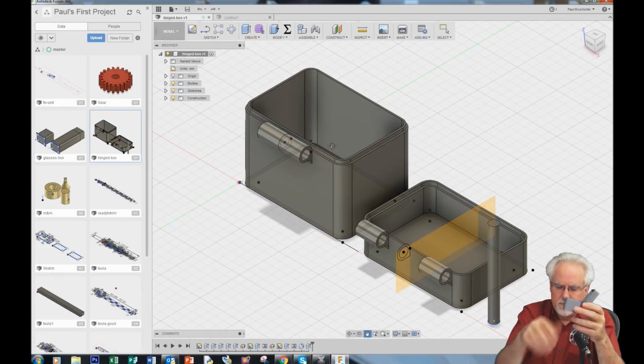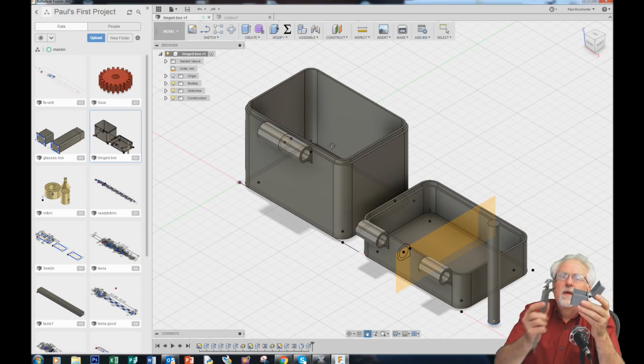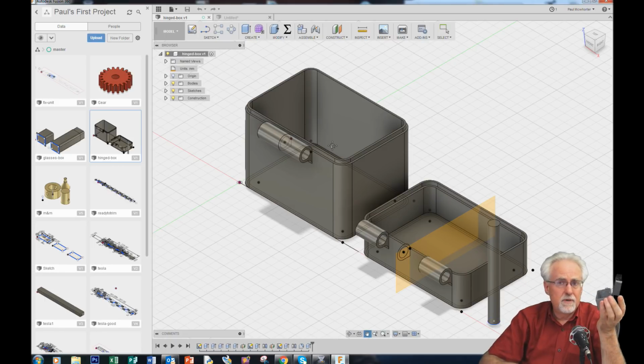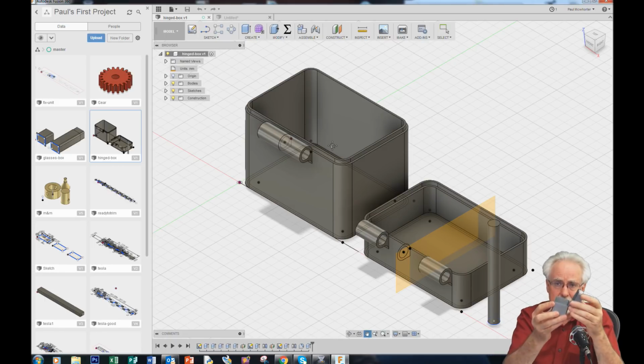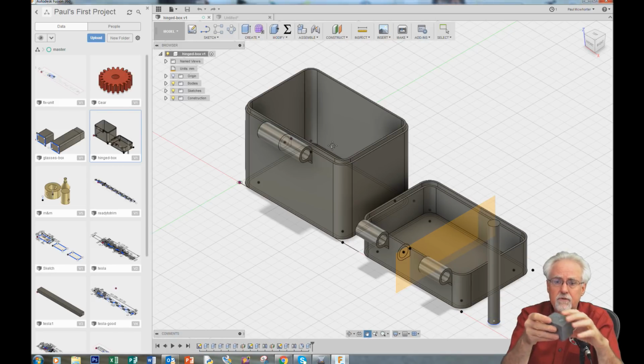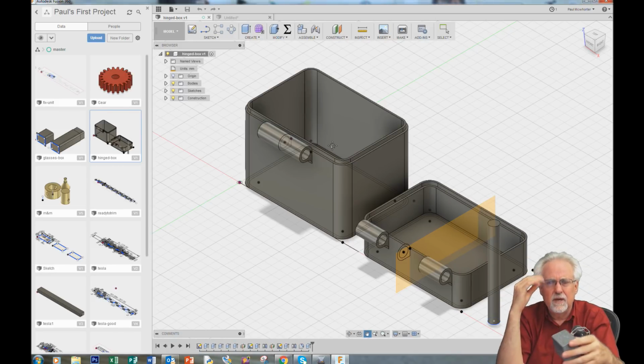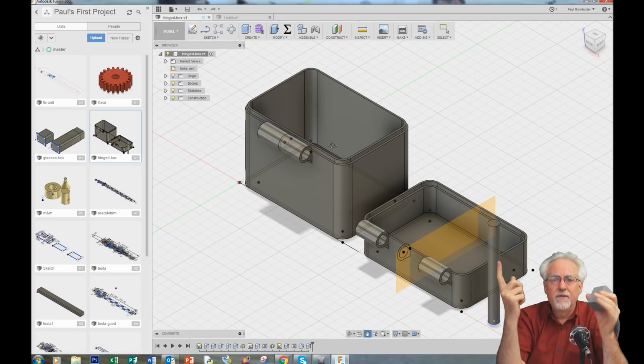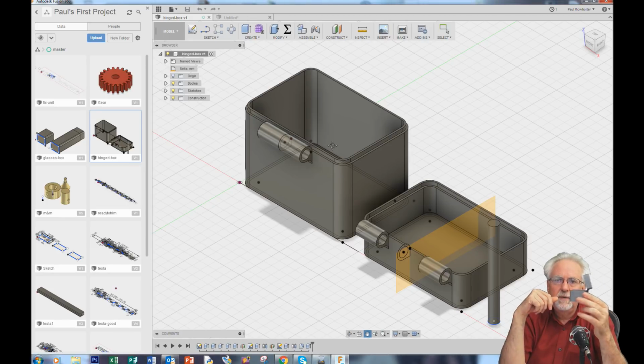All right, what are other parameters that we're going to have? Well, I'm going to have a height of the bottom, and I'm going to have a height of the top. Those are 2 parameters because the bottom might not be the same as the top. Again, I'm thinking through it. If you always wanted the seam, the break, in the middle, then the height would be 1 parameter. But because I want them independently set, it's going to be 2 parameters.